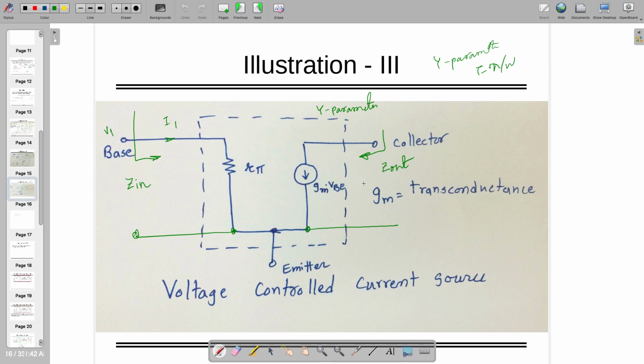Let's apply Thevenin wherever you want to see the impedance, or if you don't follow that, you can apply Z11, Z12, whatever theory you like. Gaurav, what are you going to see here? Okay, let's look at here, which is much easier. So, what are you going to see here? R pi, very good. Z in is R pi.